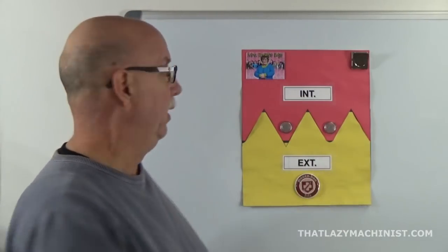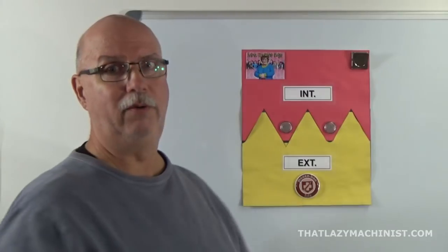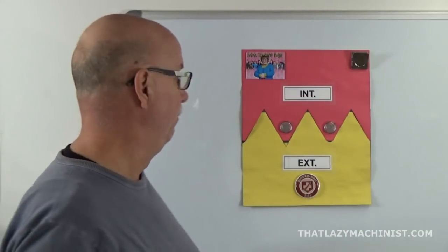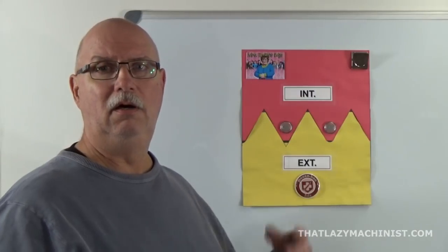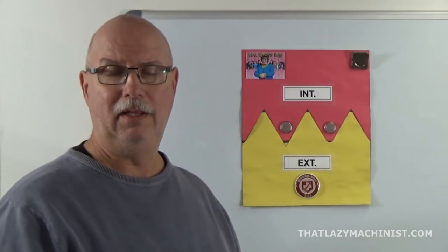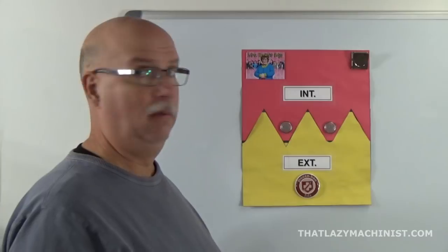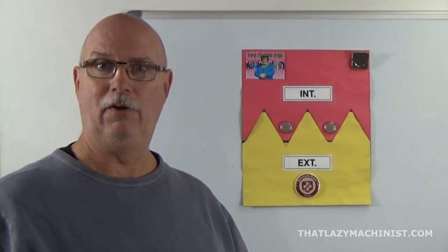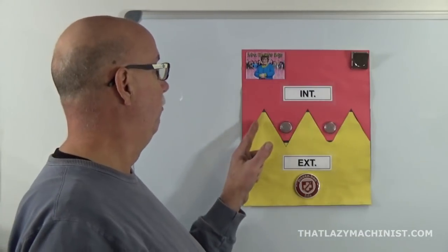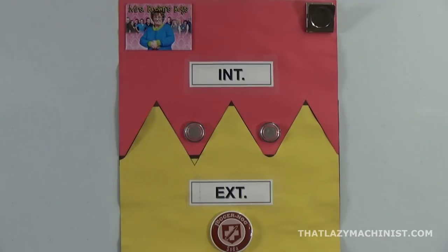But don't worry, we have a lot of clearance on the crests and roots, and that's fine. This is a representation of a class 3 thread fit. Oddly enough, a class 3, because there's 3 classes, is the one that has the least amount of play. And that would mean from 0 play to just a very little bit of play.